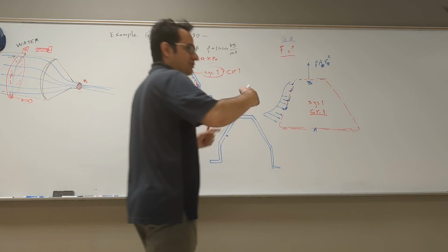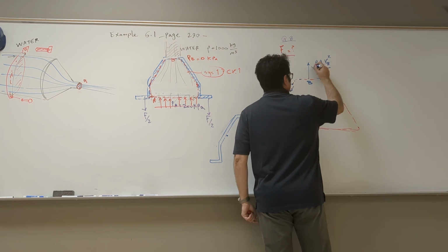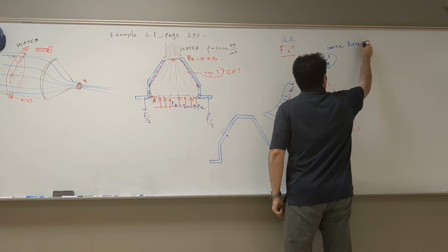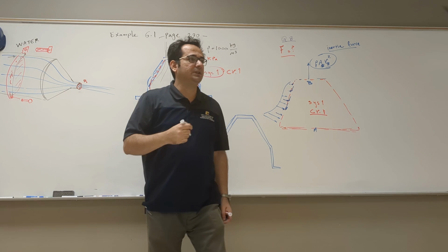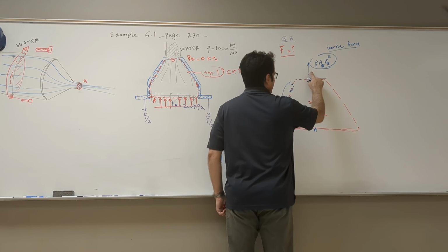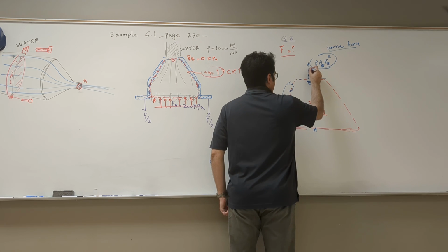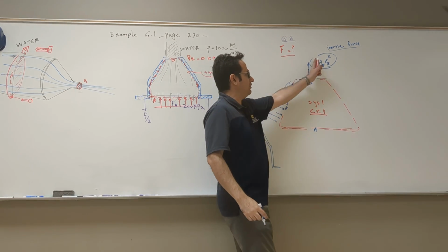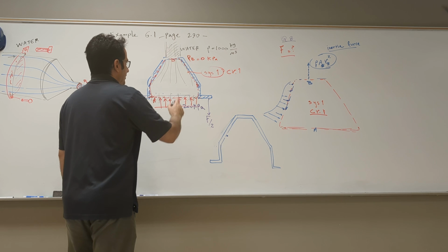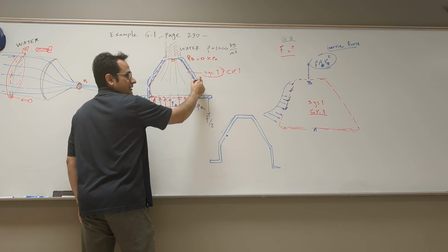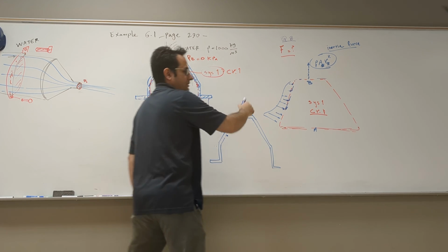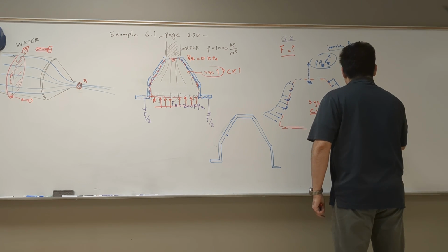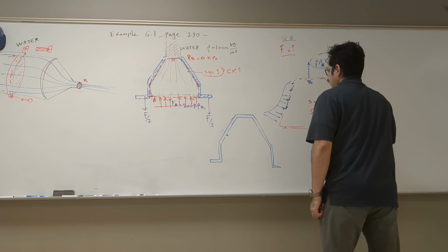Later on, I'll show you why we get the force there. It's an inertial load, not an actual touching force. Just like you did in dynamics, you add inertial loads to your FBDs, and you use a dashed vector like this to show the inertia. The real force is solid; the inertial load is dashed. Now, continue walking. What do you get here? Same thing, but on the other side.